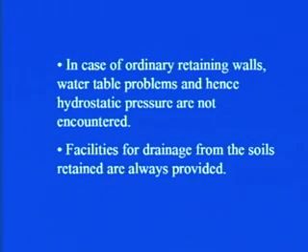Facilities for drainage from the retained soils are always provided. Why am I mentioning these points here? Because otherwise you will be wondering why we are not at all taking into account the presence, or the probability of the presence, of a water table in the analysis. We will be discussing how this drainage is taken into account in the wall towards the end of this chapter. Okay. So, for the time being you just remember that right now we are not taking into account any hydrostatic pressure which can be present in the practical field.